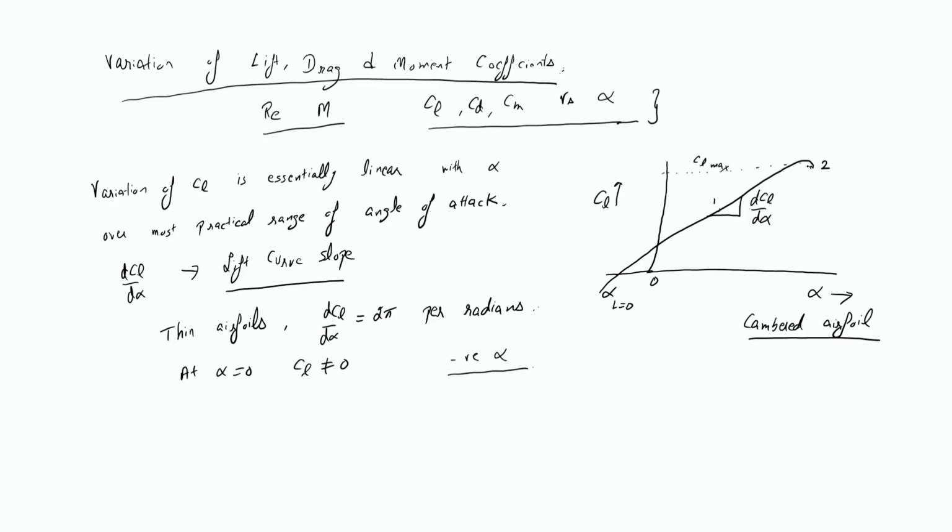Now see, up to 0.2 here the curve was actually linear, but after 0.2, what is happening over here? It is drastically losing the lift at 0.2. So at 0.2, flow separation is happening, and this flow separation we call stall. This condition is called the stalling condition. Alright. Now let me draw the figure here.